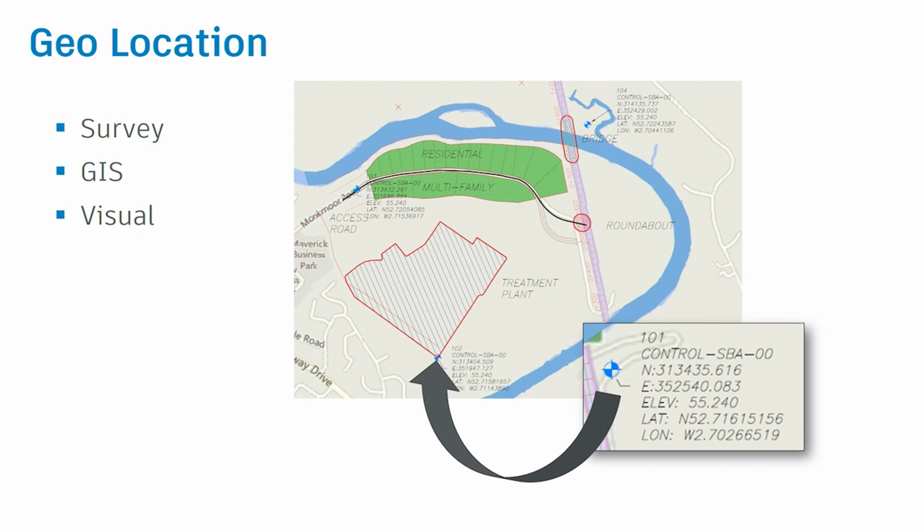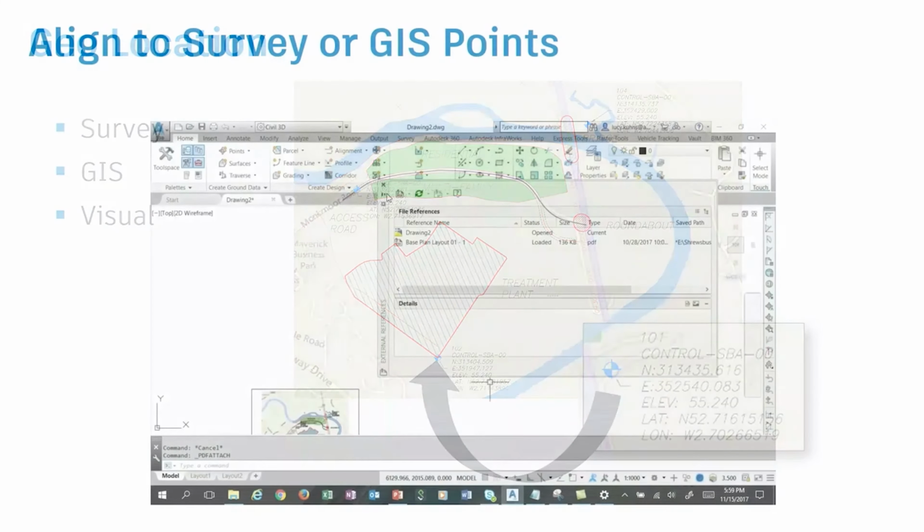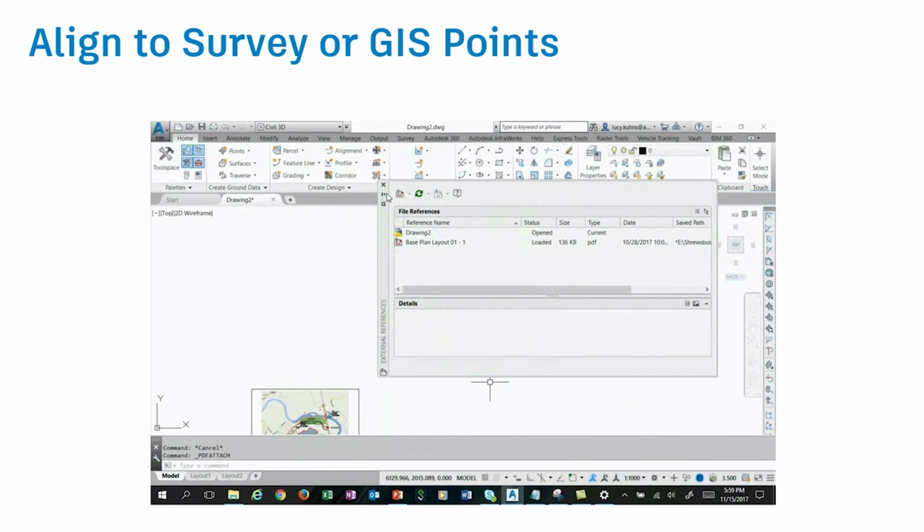Okay, now, before we get started, we need to know how we're going to tie our vertical infrastructure to our base map and our base plan. And so we have decided that this is going to be our common point. In Revit, that common point is going to be called what? The survey point. Okay, very good. That's going to be our point of reference, and you're going to see how we're going to carry that point of reference throughout this modeling.